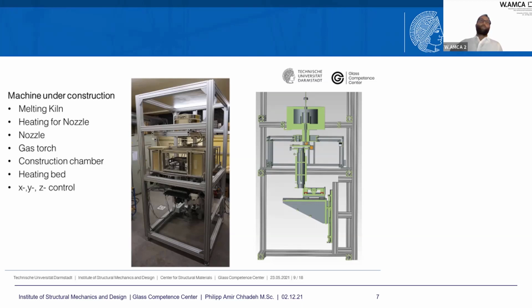In the oven, the chamber temperature is then also around 500 to 600 degrees, and there we have a controlled cooling process. The other issue I see here is that we cannot always wait 2 days to get the specimen out of the printer. So we just put another oven next to our 3D printer, take the specimen out, put the printed specimen into our oven and anneal it there.